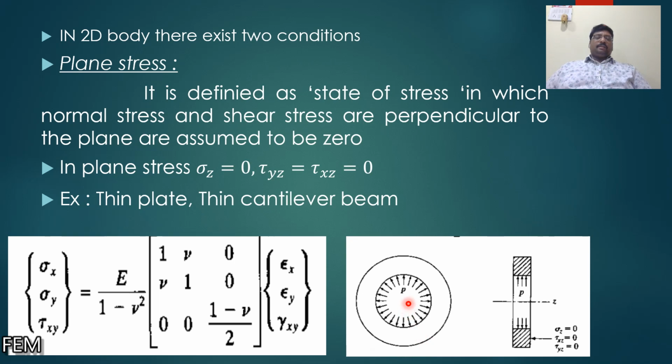That means deformation is produced in the x direction and deformation is produced in the y direction. When the plate enlarges, the thickness of the plate is going to be reduced. Okay. Whenever the dimension changes, strain will be developed in that direction. When strain is developed, correspondingly the stress also develops in that particular direction.